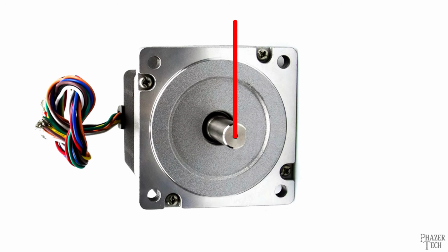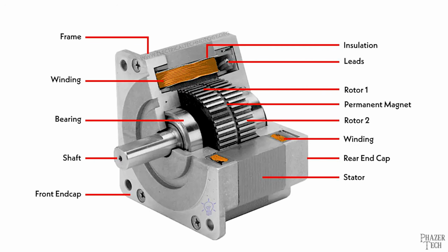While this might be possible with a regular brushless motor, it's not always guaranteed to return to the exact same position, and there likely will be some error, even if the error is extremely tiny. But depending on the application it's being used for, even the smallest amount of error might be a problem, which is why stepper motors are used in these applications that require exact positioning.